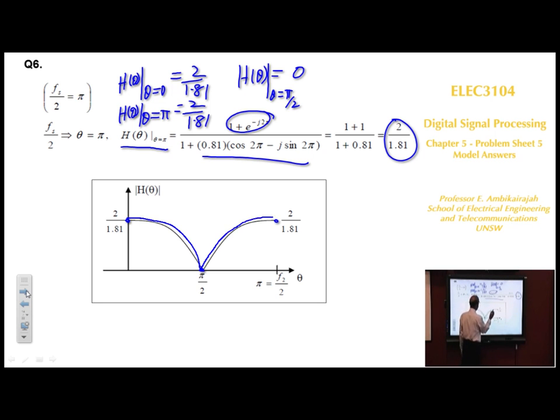It's notched the value and comes out. So notching means removing one frequency. That's why it's called a notch filter. So if you have a 50 hertz signal and you want to remove it, you use a filter such that the notch is at 50 hertz. So 50 hertz is no longer there in the signal. So it's a notch filter example. Not a design. I haven't done the design of a notch filter for you yet, but you should be able to plot, and looking at the maximum response, you should be able to tell what filter it is.